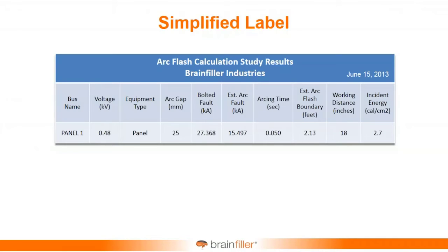You're going to have an arc flash boundary. And someday, you may go back and review, revisit, rerun the analysis. And when that happens, numbers can change. Short circuit currents may go up or down. Clearing times may go up or down. And the incident energy and the arc flash boundary may go up or down.